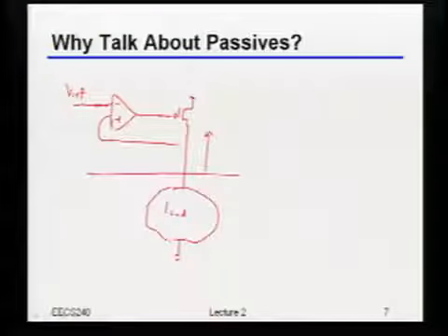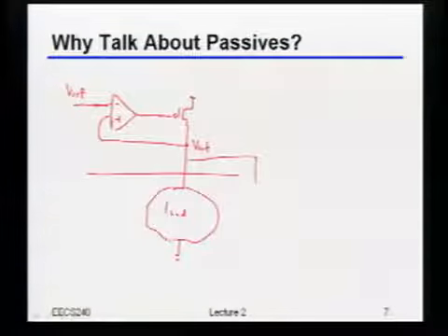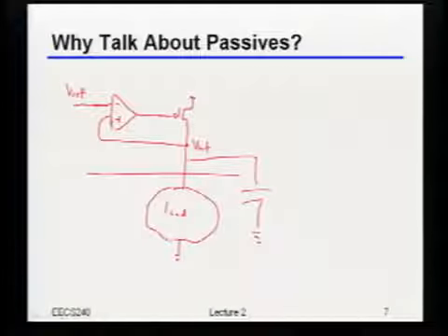A cap, okay. Where do you want to put the cap? So you want to put a cap on this so-called V out, and presumably you want to put that to ground, right? Why do you want that cap? To regulate the supply. You don't want instantaneous changes. Okay, so that's usually called a decoupling capacitor. You want to make sure the output stays relatively constant, so let's call that C decap. I agree with you, you probably want that cap. Any other passive components you might want here?